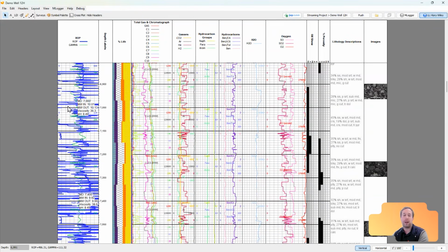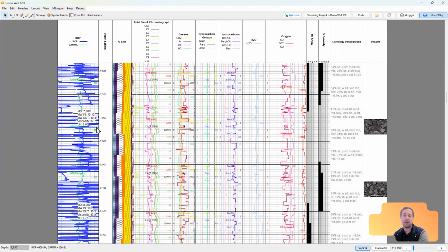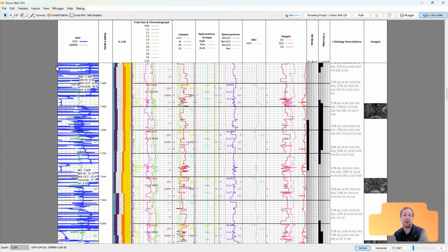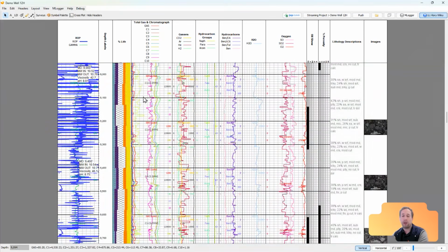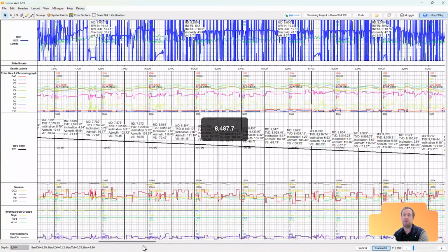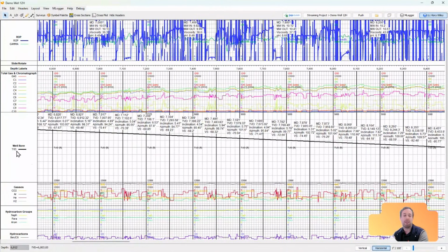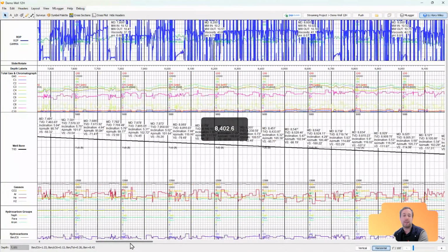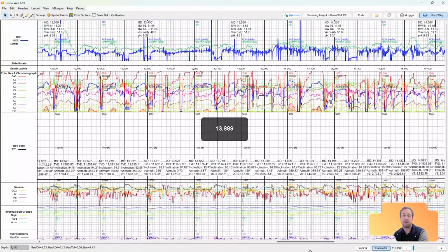We can also display information about surveys or the drilling variables. We can make really any kind of note we want here in TLog. And the wells can be displayed either vertically like we're seeing here, or we can switch to display the mud logs horizontally, which some people prefer when you're in the lateral portion of the well. Here you can see we're plotting the survey TVD, so you can see the wellbore as we land the curve and then get into the lateral section of the well.